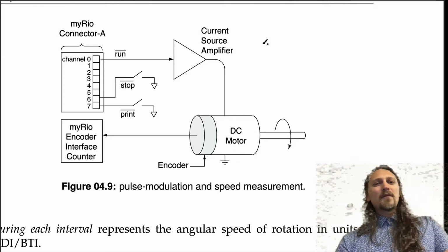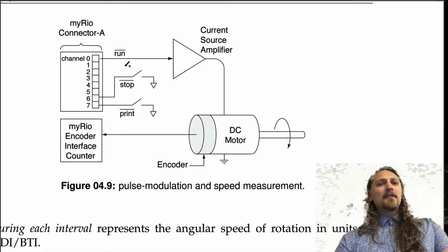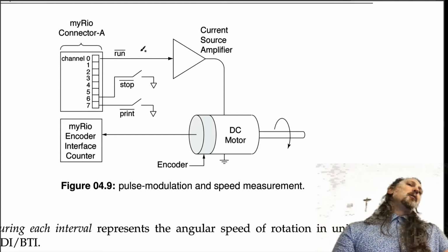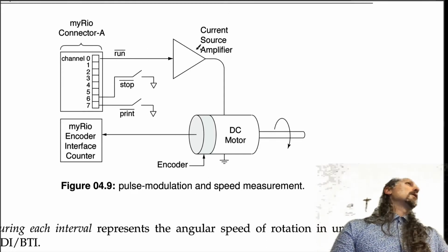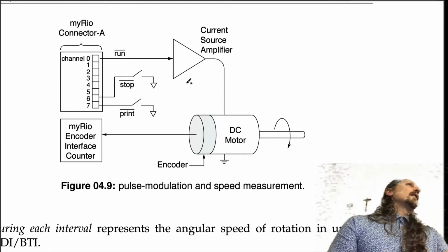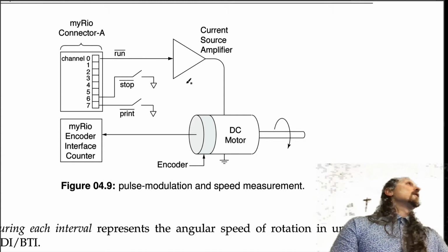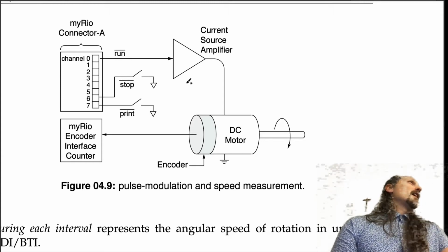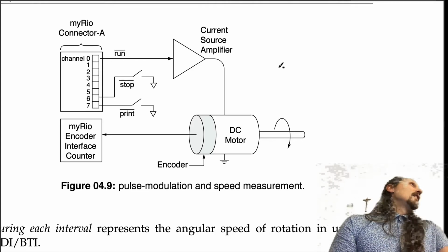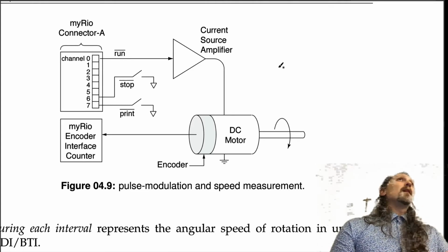It's kind of fun. So we're going to use the analog amplifier, and we're going to roll our own PWM on this, which totally works. It's just not how you would usually use an analog amplifier. An analog amplifier that can switch on and off quickly, which this one can, you can run PWM through it.